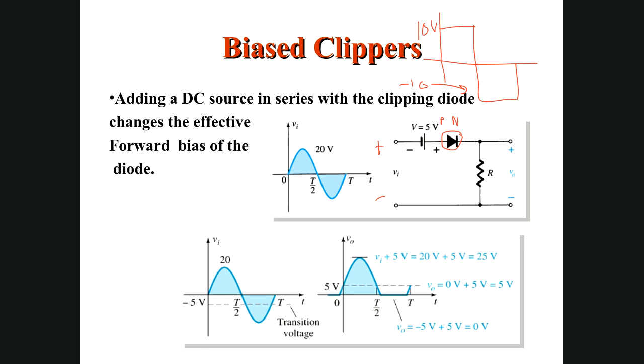So how much is the voltage? We don't know, so let us put KVL. Now here the voltage is VO, which means here also the voltage is VO. Let us put KVL here, starting from this point. What is the input voltage? The input voltage is 10. So if you go from this point in the clockwise direction, in place of VI we can say minus 10. Why is it minus?